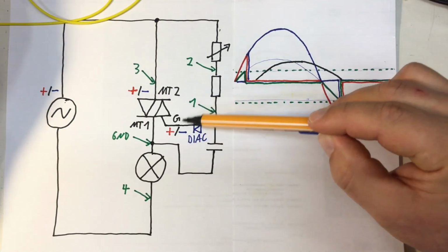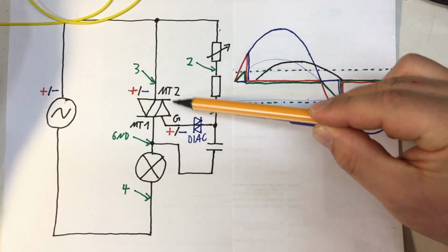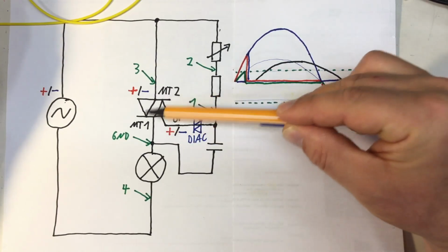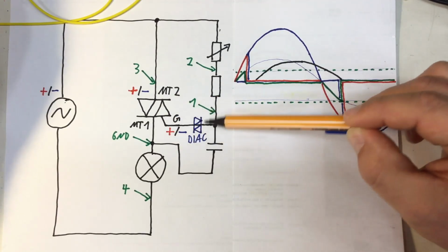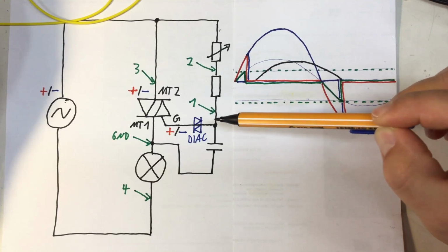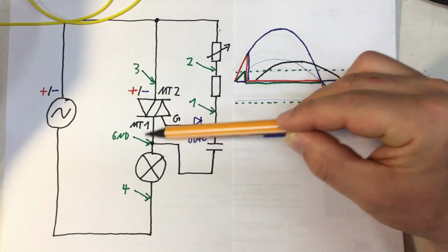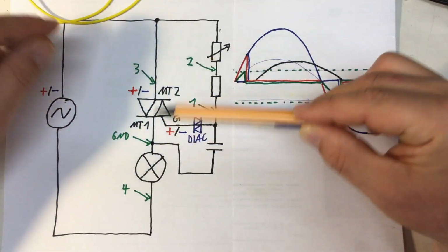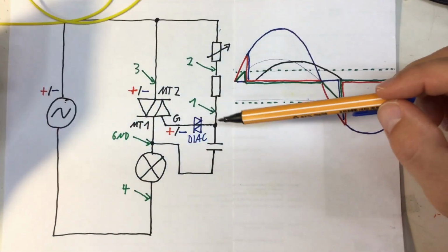And this behavior will totally dominate any asymmetries you have in the TRIAC regarding the required gate trigger current or the required gate trigger voltage. This will hold off any trigger current until the voltage here is big enough to supply enough trigger current, whatever quadrant you are in, 1 or 3. So the asymmetry problem will be solved.